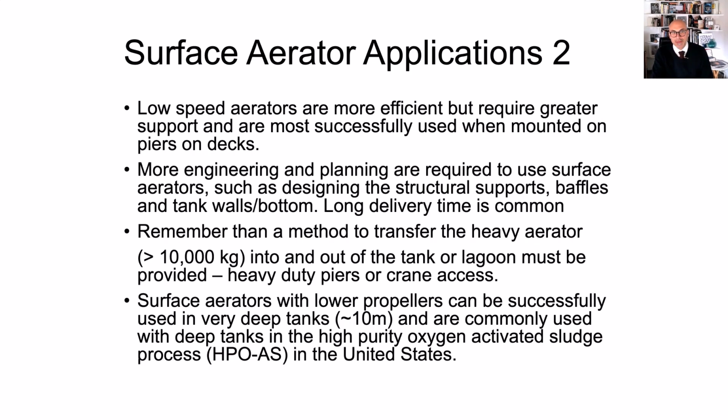And the low-speed aerators are more efficient than high-speed ones. They have larger rotors, but they require structural elements to hold them up, because they're very heavy due to the motor and gearbox assembly. It could be tons of weight. So that's one of the issues. And also they're usually manufactured upon order, so it takes longer to get them delivered.